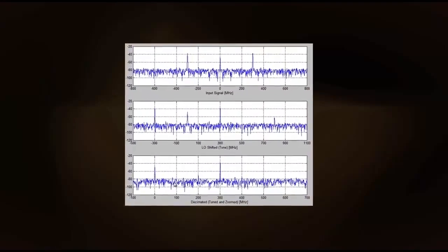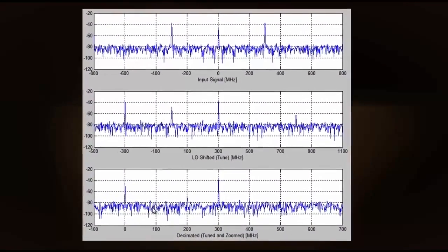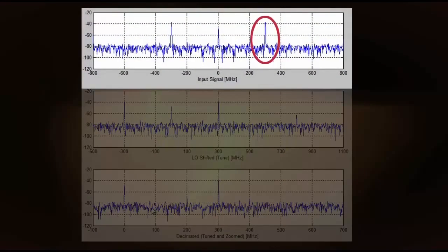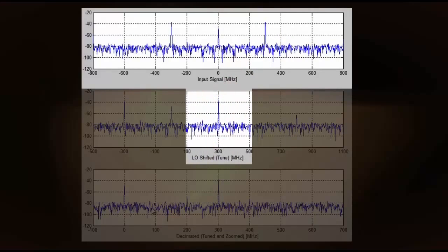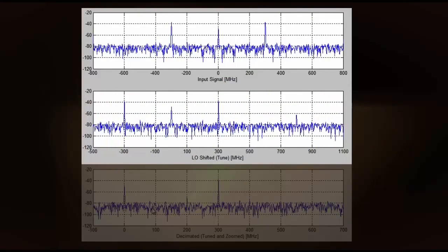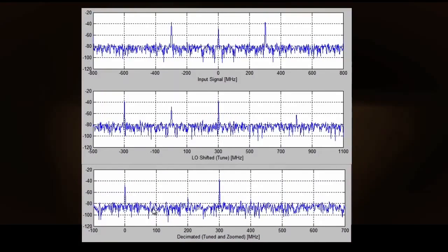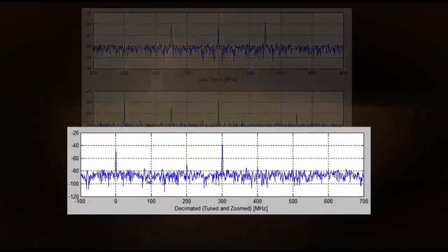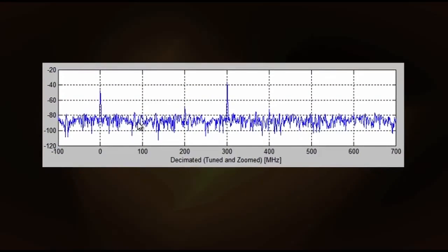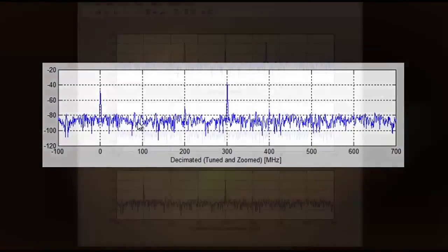Agilent's digital down conversion, or DDC, provides three key functions. It sets the analysis bandwidth around the signal of interest by shifting the center frequency in the DC to 2 GHz frequency range. It reduces the bandwidth and sample rate to the appropriate values for the signal being analyzed, and triggers on the signal of interest at a specified frequency and bandwidth thanks to the magnitude trigger.